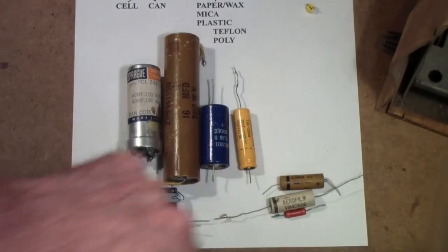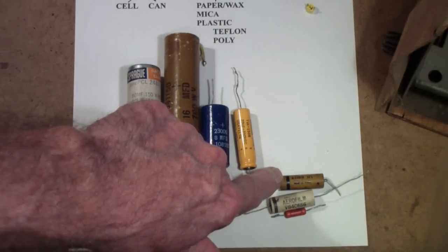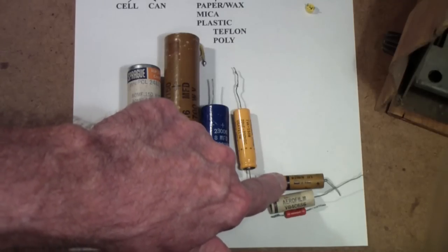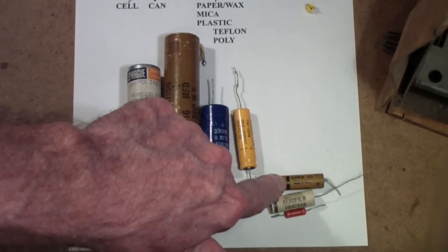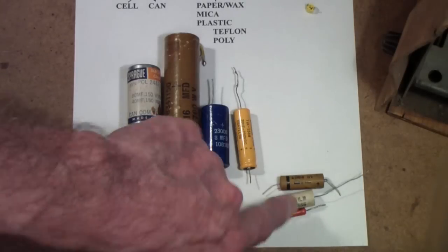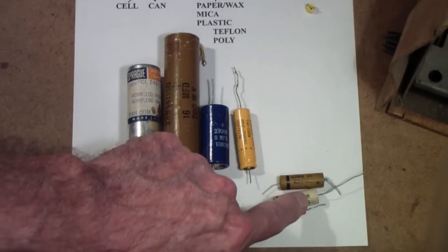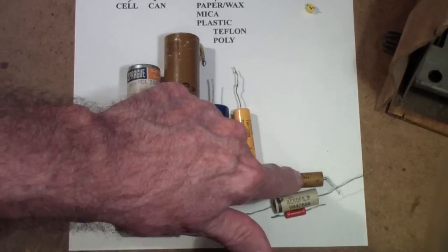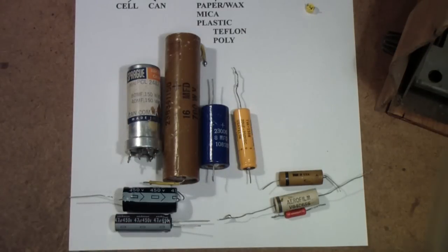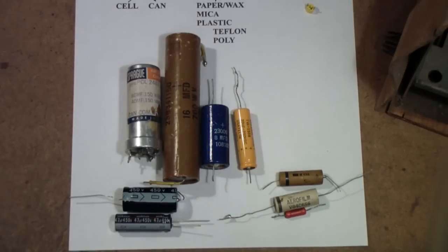Okay, over here are three types of capacitors. The one at the top is a wax paper capacitor, and you'll notice there's a little black band. That's generally called the outside foil, and that should be connected to the ground end of the circuit. Mr. Carlson talks a lot more about this, so I won't go any further. Similarly, this one is a different one. This has a hard case. By the way, these you can tell because if you touch them with your fingernail, you'll see that they just have a wax outer coating, and under that is paper. So you can literally crush those in your fingers if you push hard enough.